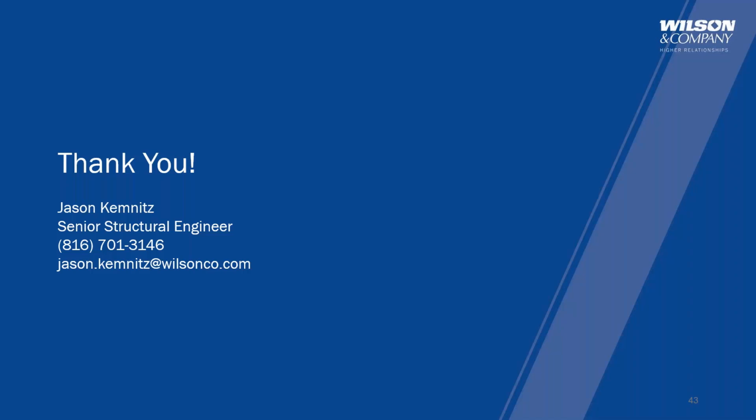Okay. Question came in beforehand: today's training is about steel girder systems. Does a similar system exist for pre-stressed concrete girders? Yeah, I would say it's the same system. It's what pre-stress has been using for years. It's just kind of mind-blowing that we haven't been using it for steel more so. So it's really the same concept. If you look at the detail for a concrete diaphragm for pre-stress versus the one we're using for steel, the difference might be that on a pre-stress, you don't have those end plates. Typically on pre-stress, you have much more end area to transfer that stress in a compression block. So yeah, it's pretty much the same concept.